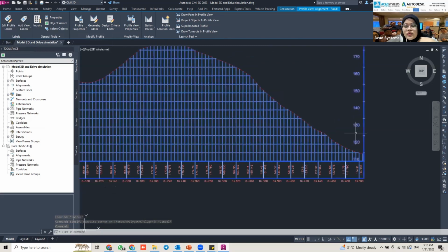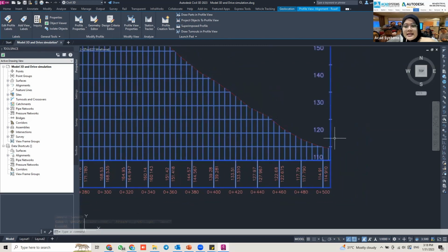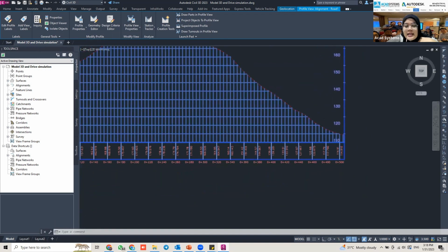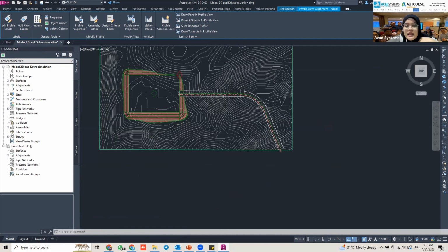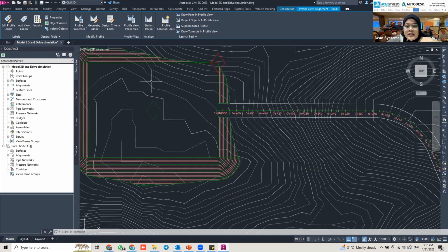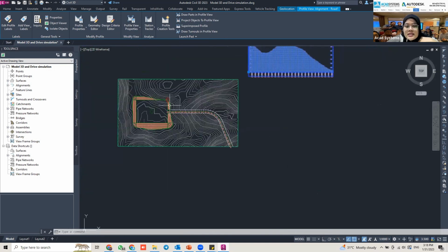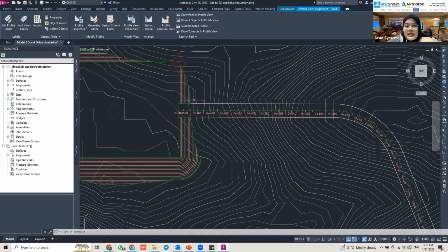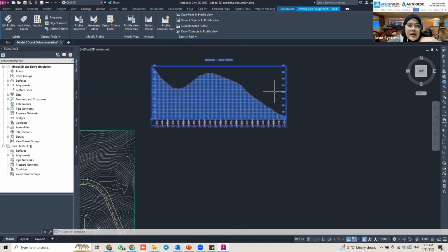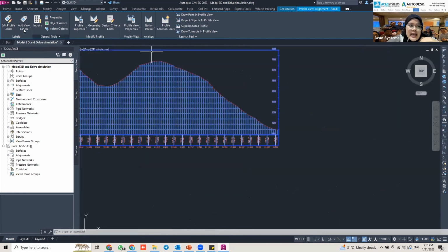I want to enter the level for elevation according to this lot here. Okay, so this route will be exactly aligned with the lot here. Okay, so I'm going to go to this add view level drop down here and go to station elevation.